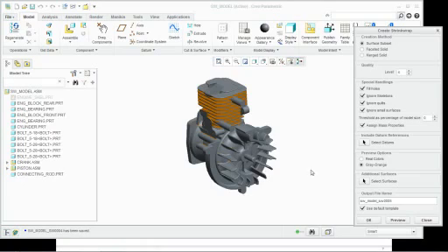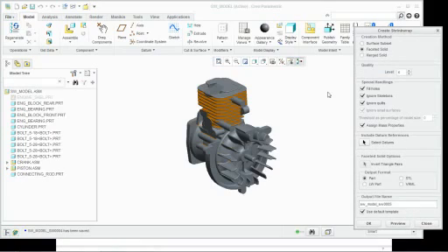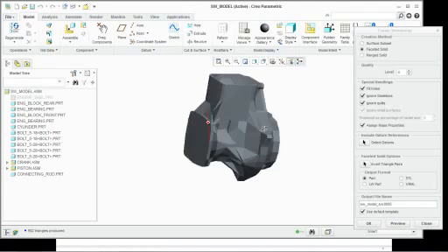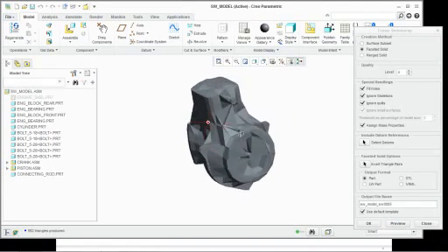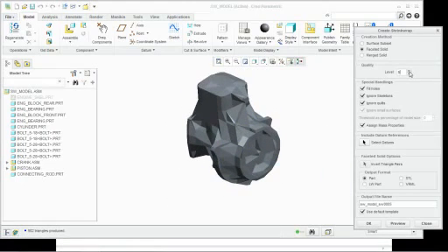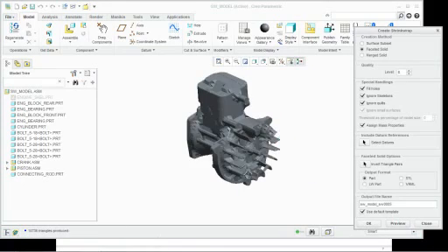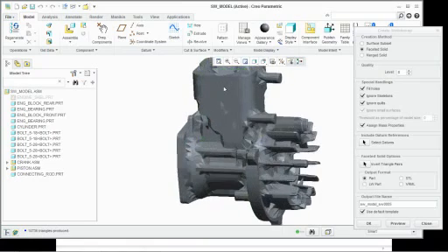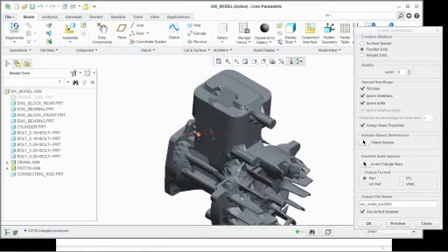And we have another type of option. So we just created one. I'm going to now create a faceted solid. And this time we're going to click Preview, leaving that at level 4. Notice that's not really very good looking. That's pretty horrendous actually. So let's crank up the level to maybe 8 again. Notice 982 triangles produced. Click Preview again, and you notice now that's a little more like the shape we want.